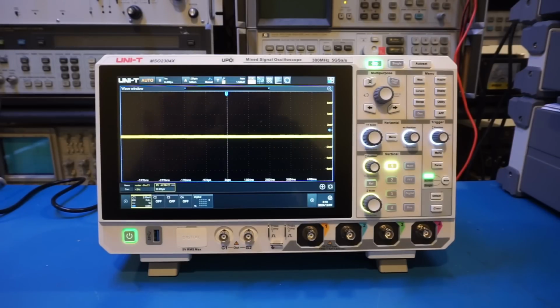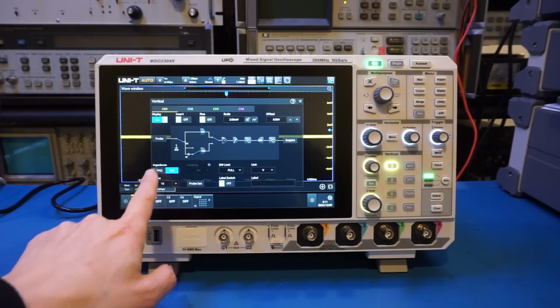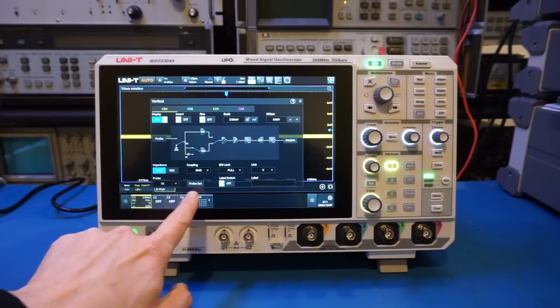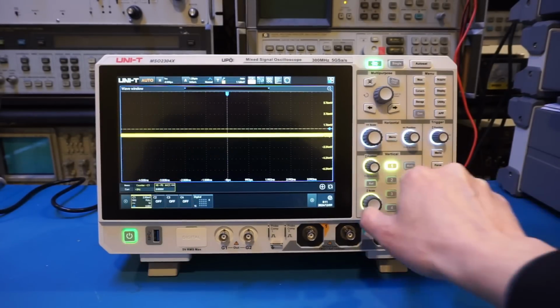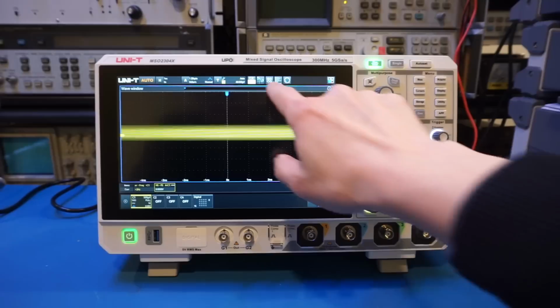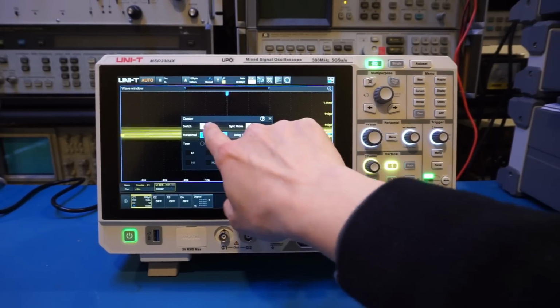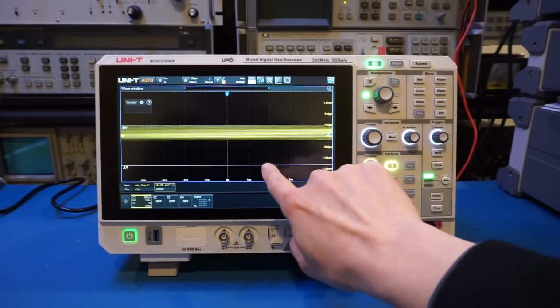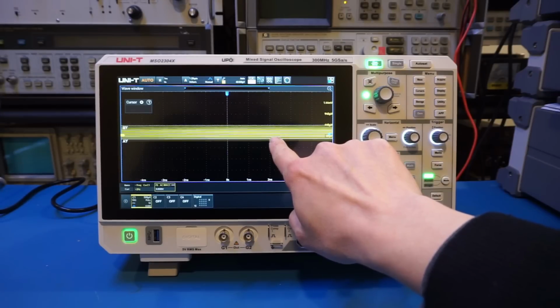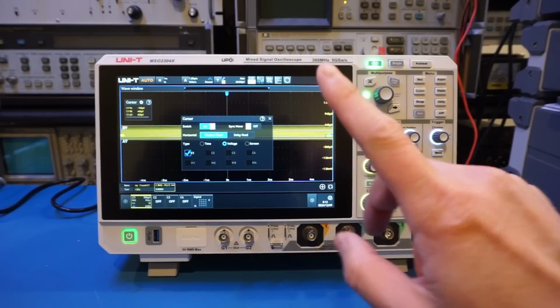And by the way, the maximum vertical sensitivity on this scope is rated at 500 microvolts per division. So let's actually take a look at the noise level at that sensitivity. For that, I'm going to go to the channel, and I'm going to actually ground it first. So let's ground it. And now channel 1 is grounded, and I'm going to increase the scale here. So right now we're at 500 microvolts per division. And let's enable the cursor. Let's do voltage. And actually, let's go back to cursor. We apply it to channel 1. So the noise level is roughly at 1 division here.